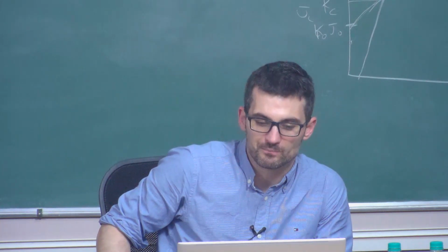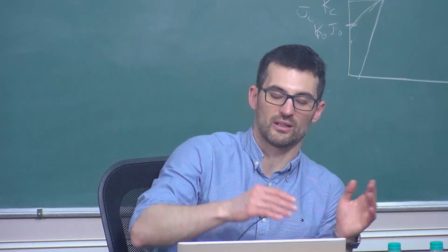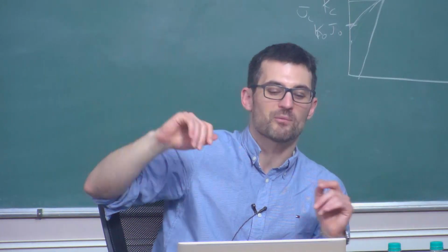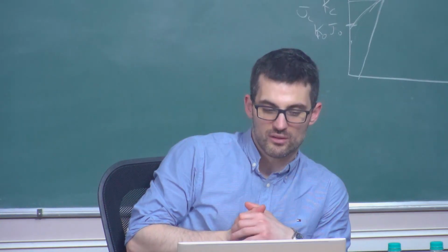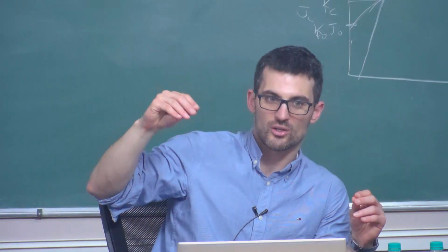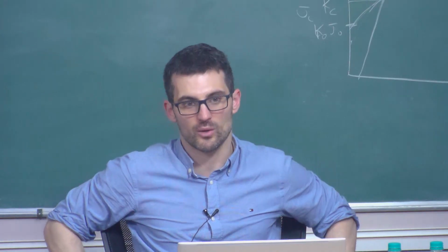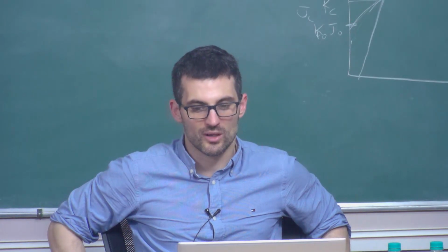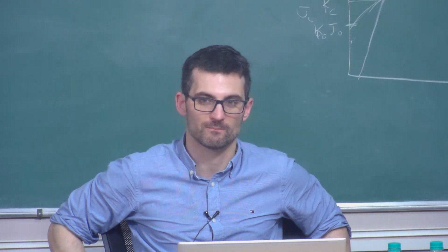I think in general, if you're talking about fracture in elastoplastic materials, this works okay, not only for small scale yielding, where K dominates, but also for J. If you are talking about shear band localization, things like this, I think these other methods where the plastic strain lowers the fracture energy seem to do a slightly better job. So if instead of fracture you're thinking of more localization phenomena, it works a bit better in this other way. Maybe I could include a slide of that on future days to show what other people are doing. So there are various approaches.